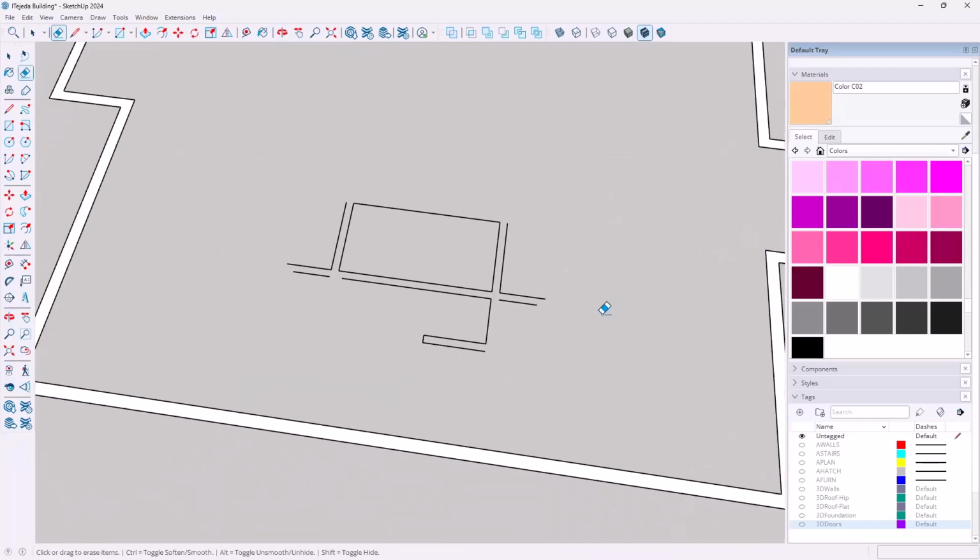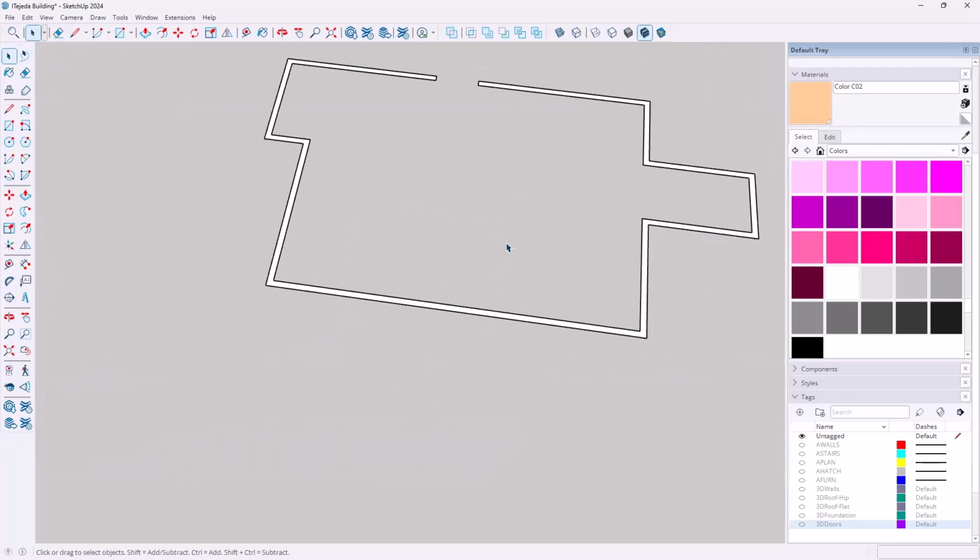And then it's easy for me to do the following. I'm going to come over here to my selection tool. And this time, instead of using my select to draw a window, I'm going to use this tool, which is my lasso select. So click on lasso select, and I'm basically just going to draw a lasso around the remaining set of lines. And then I'm releasing my mouse button, selects everything, and then I tap delete. And then I'll tap the space bar.